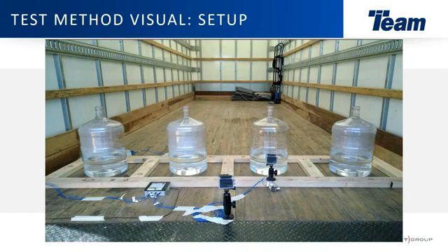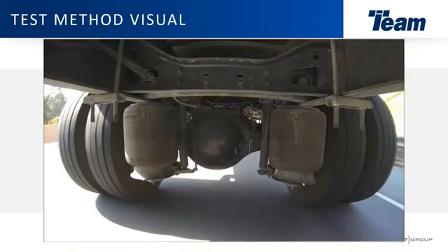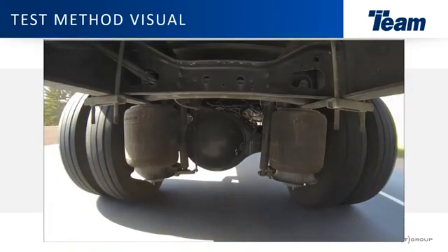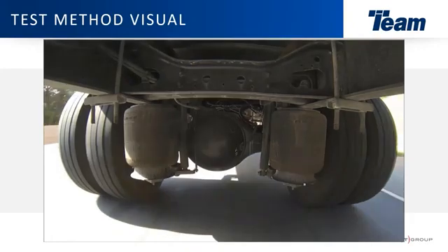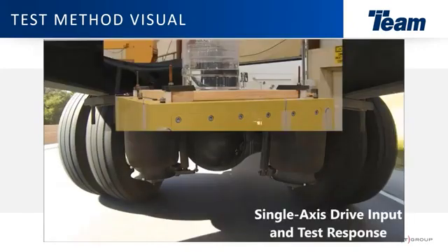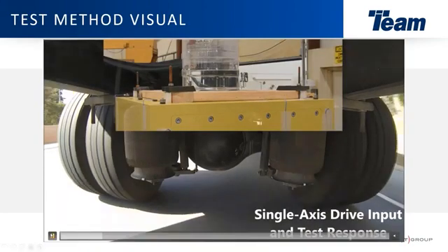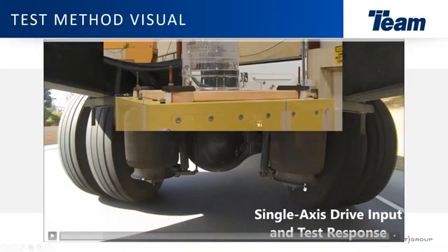And what you're going to see in this video, we're actually replicating this in the lab. So this video is another GoPro from the bottom of a truck. We actually modified this camera view using these 2 white points down here to simulate the plane that the road is on. So the video in the background is your drive input signal.